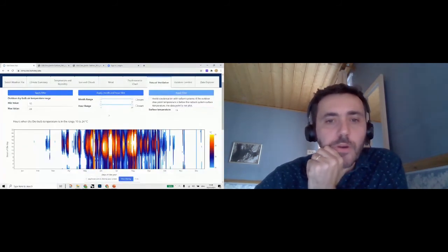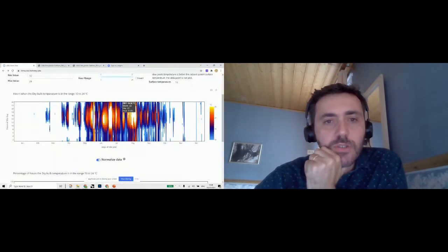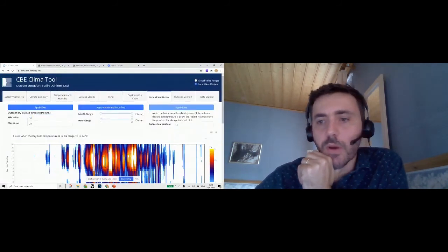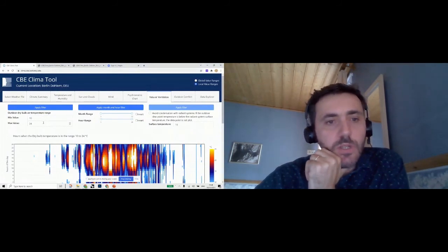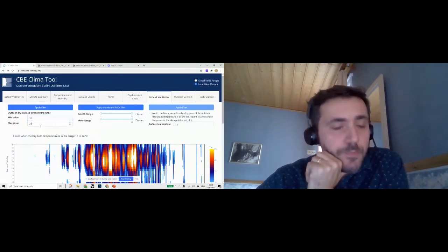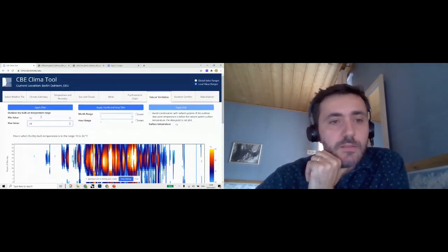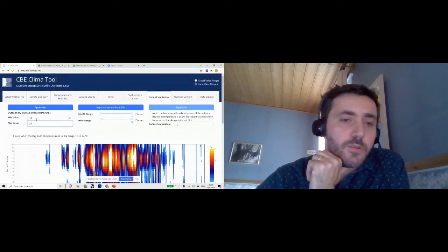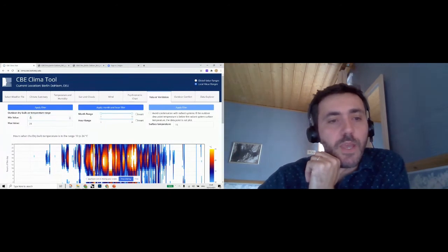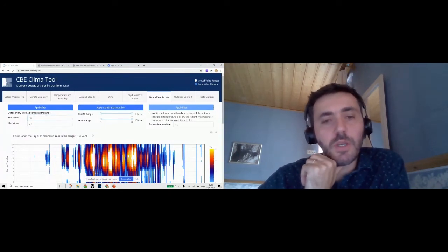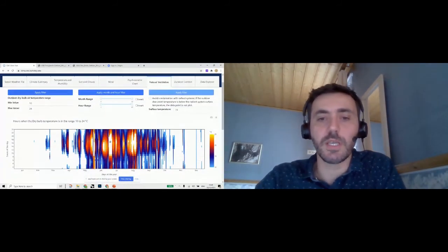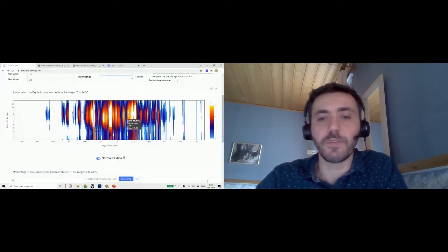Going on, we offer a natural ventilation assessment. So essentially, this is a relatively simple but quite effective assessment that says, well, natural ventilation, I can do it between a minimum and a maximum temperature. And you can look at that. Typically for an office, you would use 10 to 24 degrees. Maybe for a residential building, you would have a higher lower temperature. But essentially this tells you, based on outdoor air temperature, what is the potential for natural ventilation.